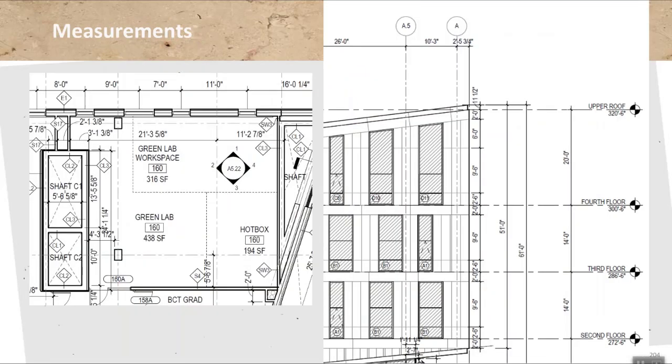Okay, so next let's take a look at measurements and how they're represented in a plan set. Again, we're using the design building as an example. So on the floor plan example that you see on the left here, you'll see the chained dimension that I talked about earlier. Typically that is given for windows, as in this case, or for interior dimensions, as in that case. And that usually allows you to figure out even in-between dimensions, through subtracting, adding, etc.